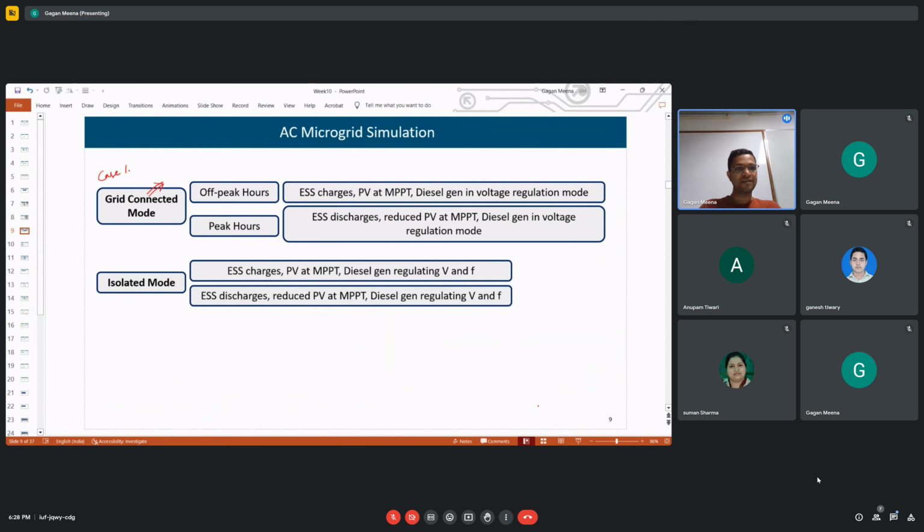So how is there a reduction in cost? Because both are autonomous microgrids, and if there was no interconnection, as we have seen in the previous case, we had to use the power from the diesel generator, which is costly. But here, because we have an interconnection, if we require that power, we can have it from the other microgrid, that is still from a PV source. That is cheaper than the diesel generator. So there is a reduction in cost in that case.